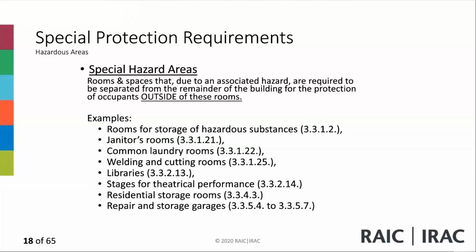Storage garage separation. A storage garage is another defined term, and we know it does not have any repair in it. A storage garage shall be separated. I'm reading right now 3.3.5.6.(1), except as permitted in 3.3.4.2.(4) and (5). Oh, I've got exceptions here. A storage garage shall be separated from other occupancies by a fire separation with a fire resistance rating of not less than 1.5 hours. So every storage garage needs to have a 1.5 hour separation.